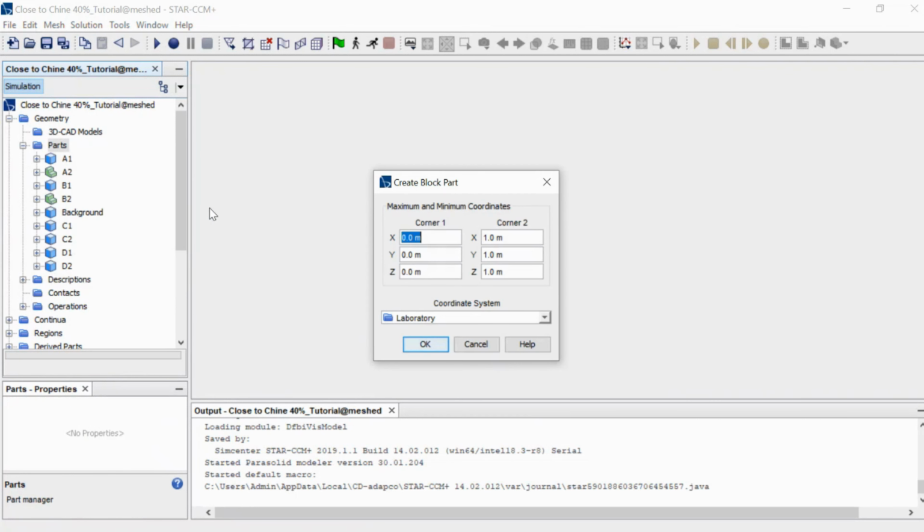Overset mesh is a mesh method using donor and acceptor cells. So, because of that, we need to create an overset box, a background, and also refinements. This method requires more than one geometry, with the background as a donor and the overset as an acceptor.